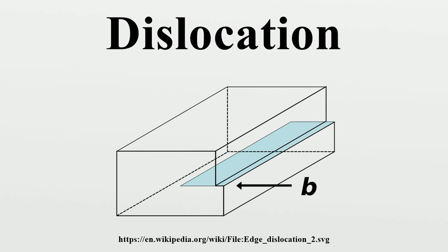Since dislocation climb results from individual atoms jumping into vacancies, climb occurs in single atom diameter increments. During positive climb, the crystal shrinks in the direction perpendicular to the extra half-plane of atoms because atoms are being removed from the half-plane. Since negative climb involves an addition of atoms to the half-plane, the crystal grows in the direction perpendicular to the half-plane. This is one main difference between slip and climb, since slip is caused by only shear stress.